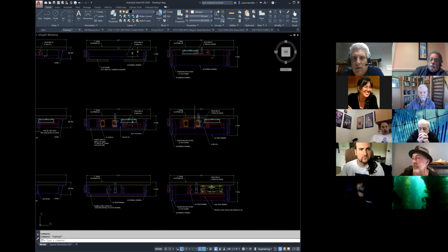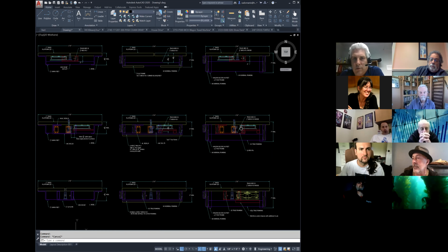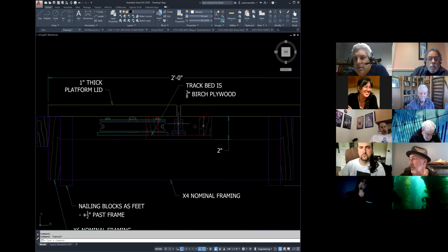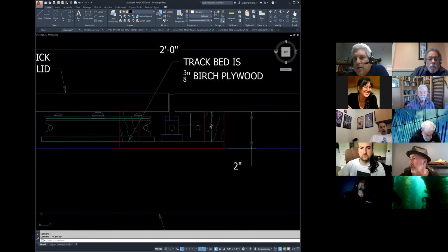And I know there were some questions on dogs. I think Loren started to bring up some pictures, but it might just be a good thing. This is not a typical Broadway style wooden framed deck with a track in it. This is just an all wood frame, wooden lids, with some kind of finished top surface. We just do a very simple wooden framed track body, we call it. And we have this dog that runs through it. And as you can see, the idea is that we have return cable on either side, and we have sheaves that allow that to fit.